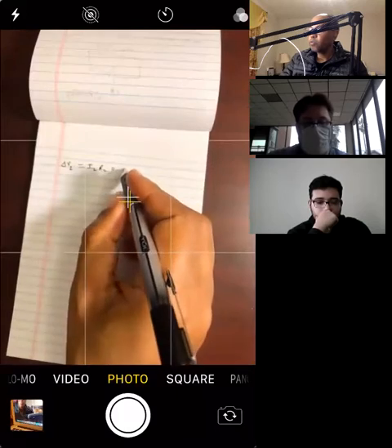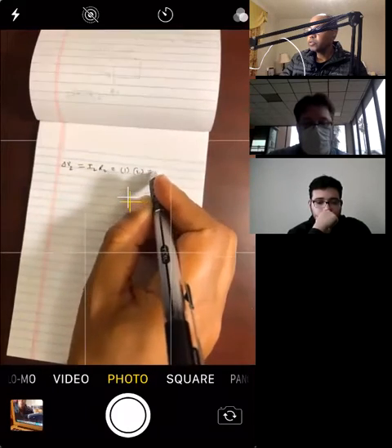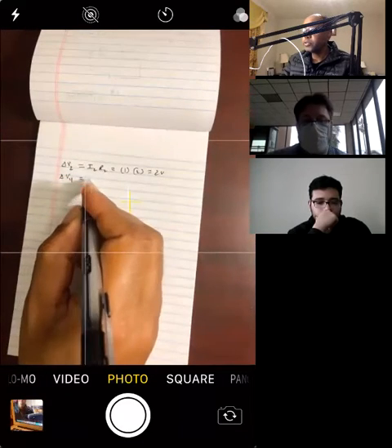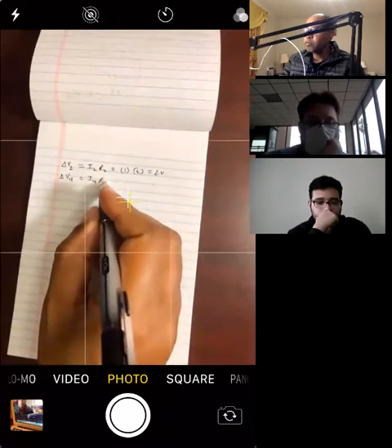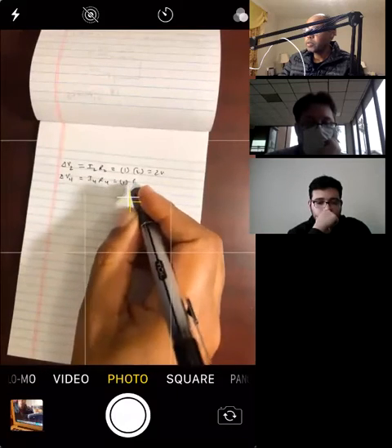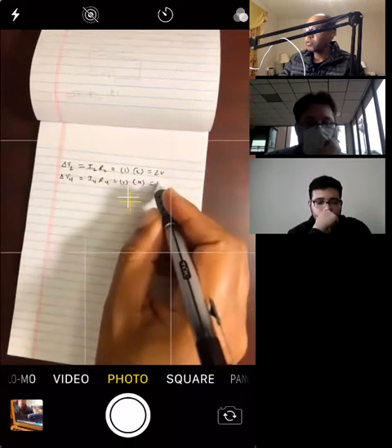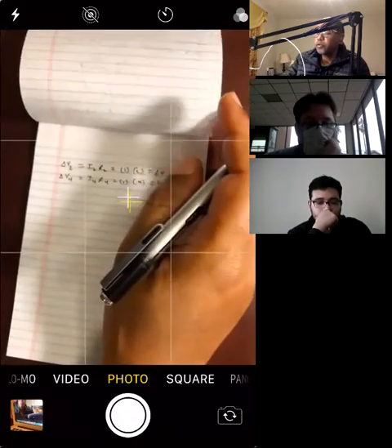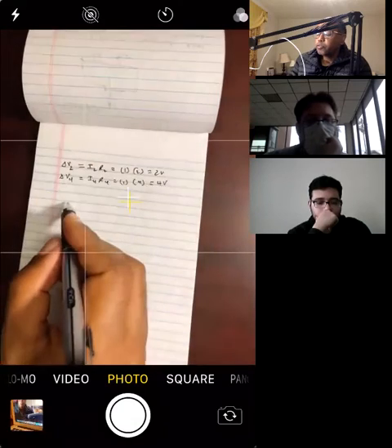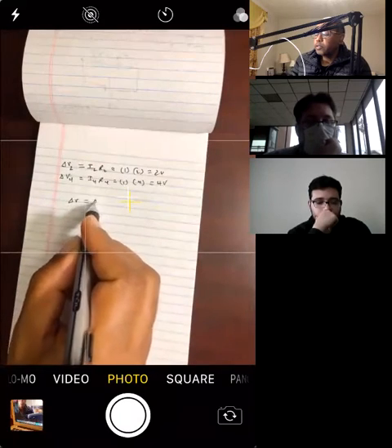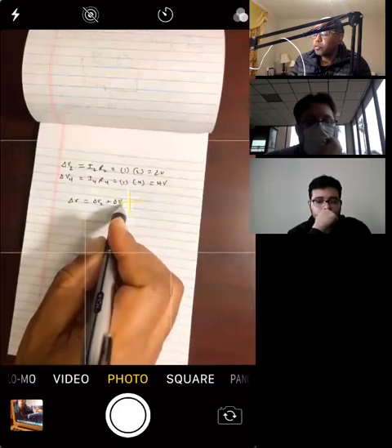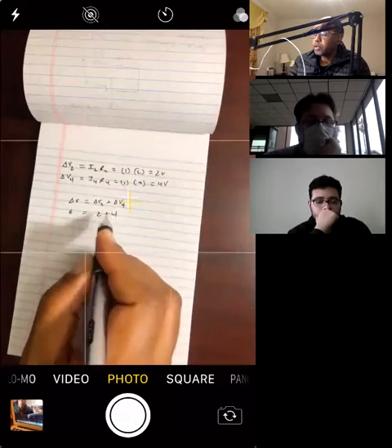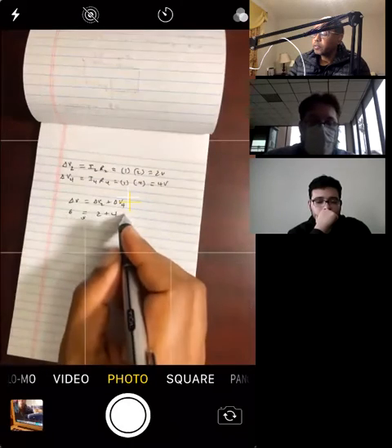That is 1 amp times 2, that is 2 volts. And the potential difference across the 4 ohm resistor is current times R4, which is 1 amp times 4, that is 4 volts. Okay, that's it. So you got the potential differences and the currents for each resistor. Now, if you want to check this formula, delta V equals delta V2 plus delta V4. This one is 6, and these are 2 plus 4. So checked, right? They add up to 6. Check.